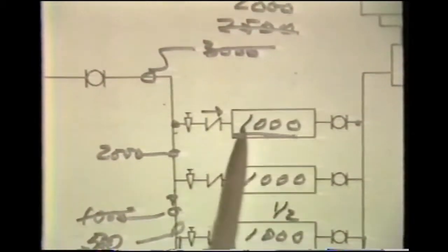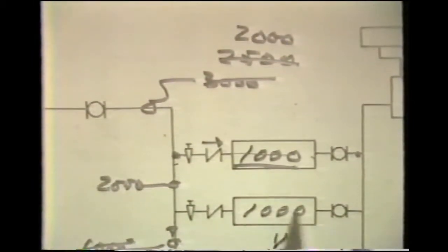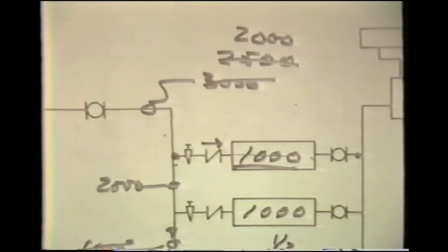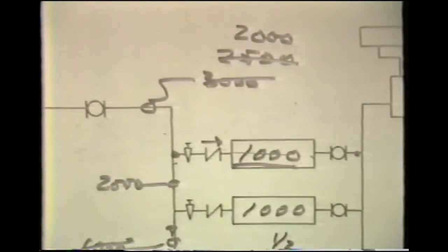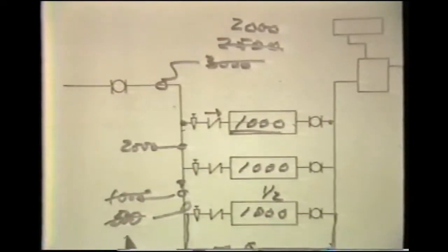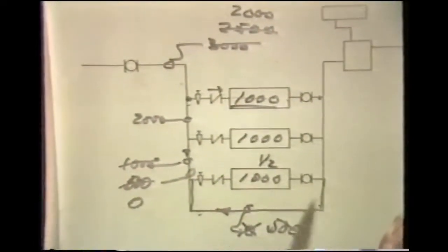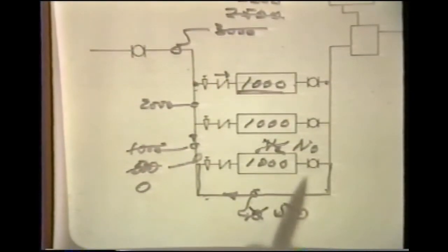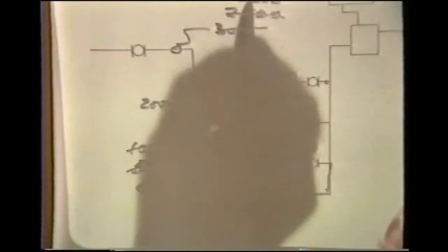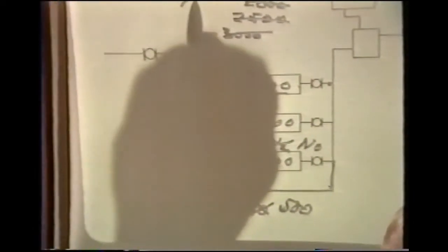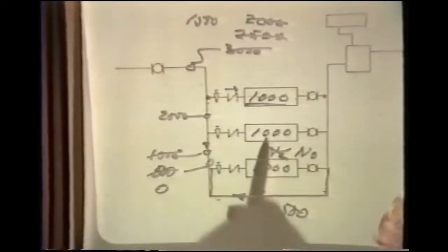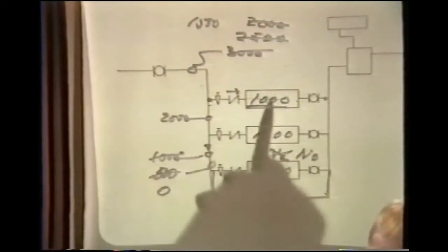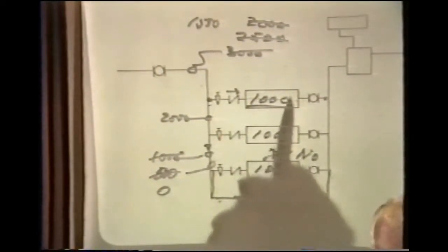If the flow rate decreased still further, down to 2,000 GPM, we would still maintain full load operation through the first two chillers, maintain 1,000 GPM through the last chiller, but we have now zero flow, and we have no load, and the chiller would simply cycle off. Again, decreasing the load further to 1,500 GPM, with only two chillers on the line, we would still maintain full load operation of the first chiller.